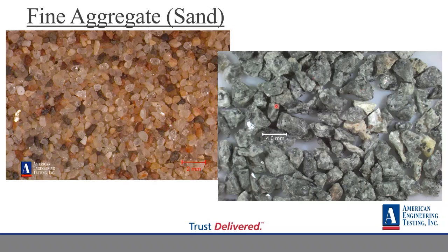Producers also do make manufactured sand, which is from what we talked about, quarries. So a quarry will crush down their product to a sand to meet that gradation standard. So there's a couple different reasons to do this. One of the main reasons, I know that I visited a quarry in an area of North Carolina where they don't have much natural sand that would meet those concrete gradations. So they do manufacture their sands out of a rock body, out of a quarry.